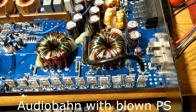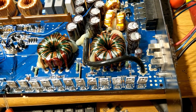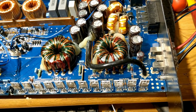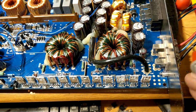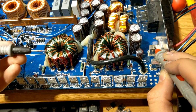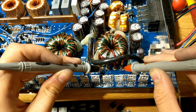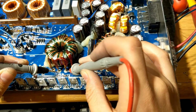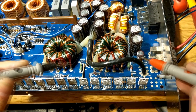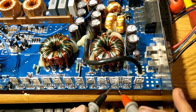So, the amplifier obviously had dead power supply transistors, as you found out. So I've replaced those now. They're all working fine. However, the problem with the amplifier, and the reason it blew, is this transformer. So 12 volts is supposed to come in here at the 12 volt terminal, goes through the fuses, and then it comes to the transformers on these two middle pins here. So you've got these two here with 12 volts on them, and these two here with 12 volts on them from the terminal. Okay, it then goes round the transformer and comes out, and it's meant to be on pin number 2 of these FETs.